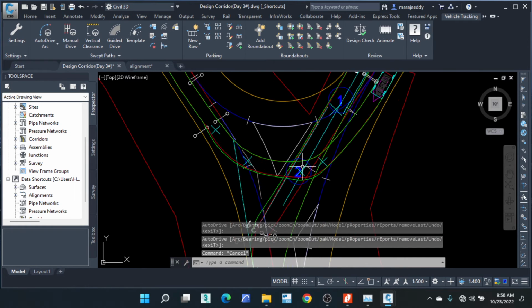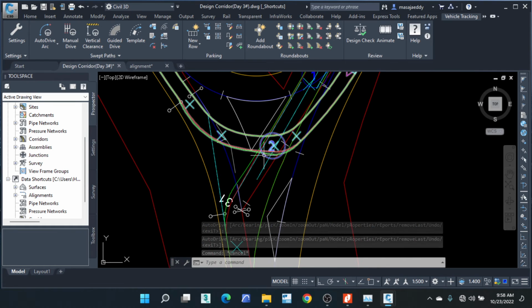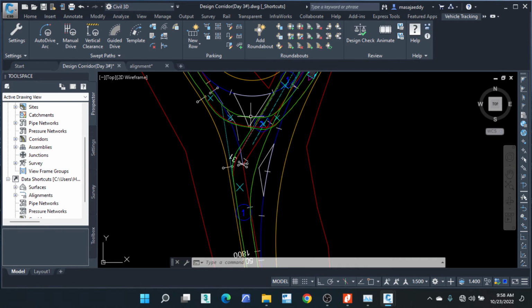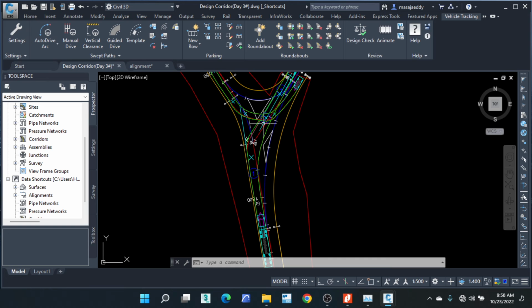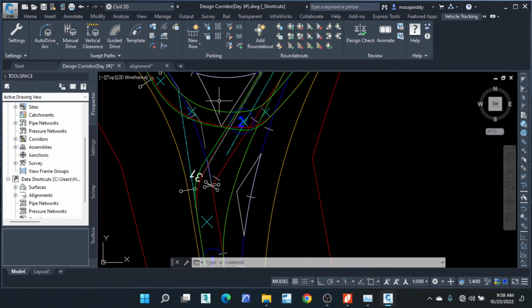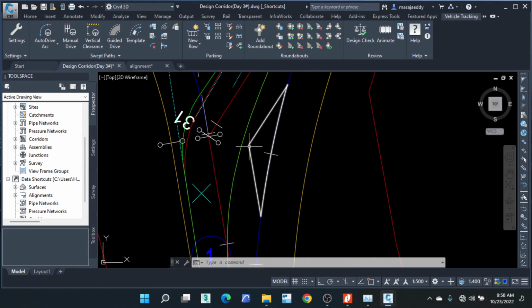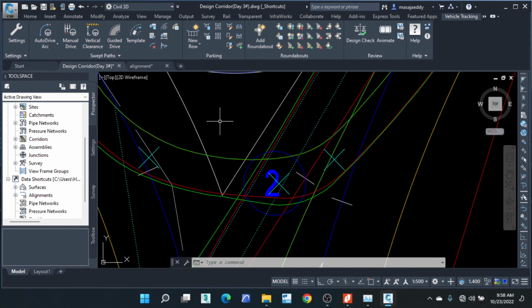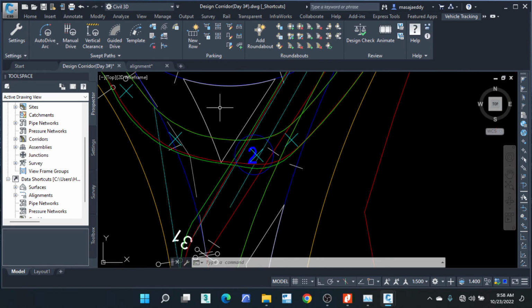So for example, for this small SUV, this is the behavior, okay? So you find that actually it's overlapping our island, in this case for it to have a comfortable maneuver for the corner. So since it's overlapping, you are going to be able to chamfer our polyline in a way that respects this curve. Okay. So what we are going to do for this one, it's okay. We can have a very small curve radius, but for this area, we have to chamfer. So we are going to chamfer this area with different radius.